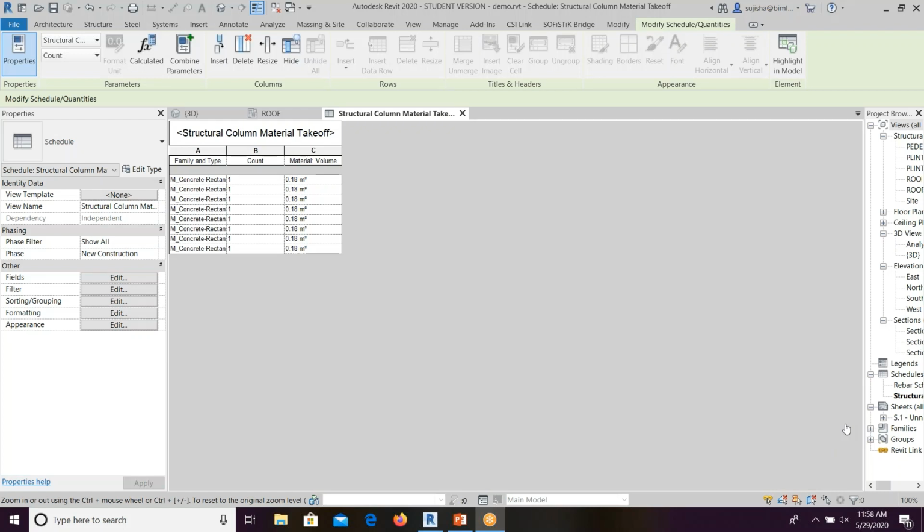The same way you apply in ETABS, you can apply in Revit also. So I don't feel it is difficult. You can apply it and directly take it through the CSI link option. Everything will be exported, so you can use that model. You can check the model, run the model and design it. It won't be difficult.